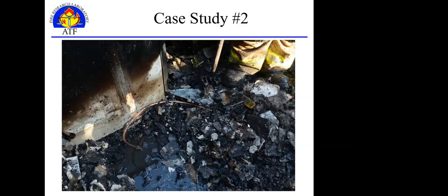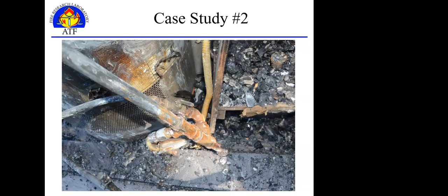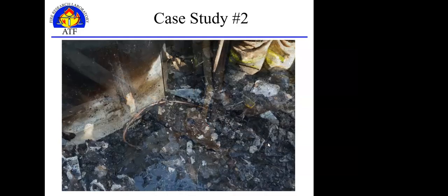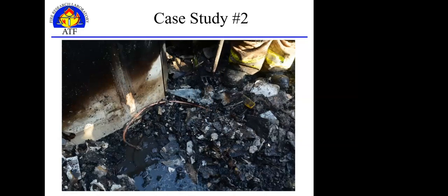So if the homeowner was replacing this water heater and wasn't careful, he either accidentally or intentionally, thinking this valve served the water heater itself, turned this back on, and that allowed that 1/2-inch copper line to free flow into the basement. And then a certain amount of time later, the place blew up.